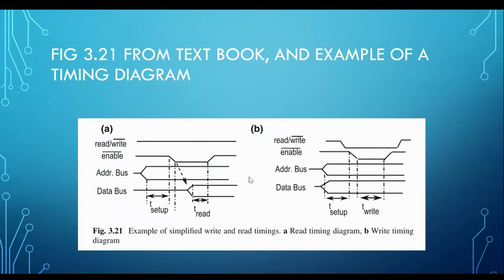For this device, whether you can read or write, you have to do it only at certain times. When the address reaches high or the data reaches low or whatsoever, there is a specific window for you to write and read. So it depends on this timing. The timing diagram shows you when information must be sent and when it must be received.